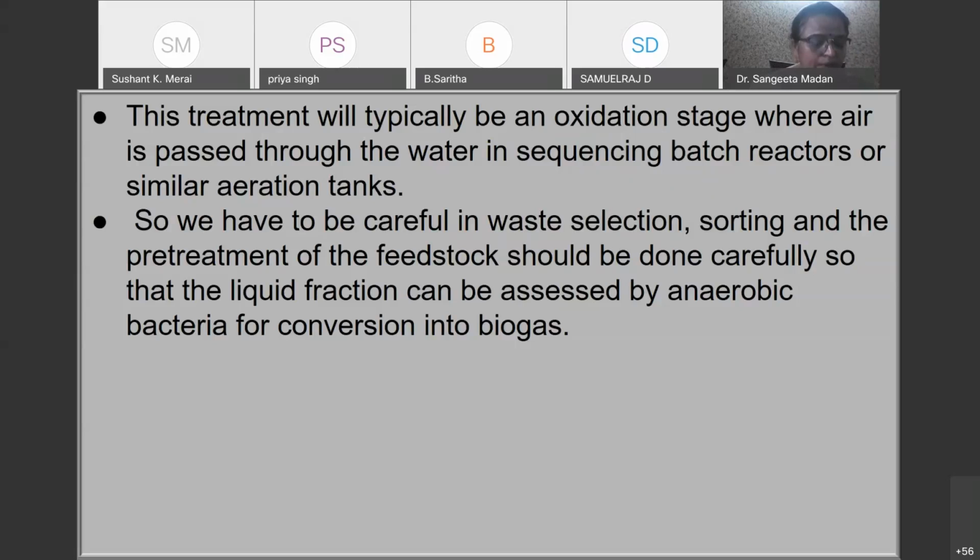So it needs to be continuously used, because we face difficulty in storing it. Biogas lamps have lower efficiency as compared to using kerosene. Gas production below 15 degrees centigrade is no longer economically feasible. If your gas production is low, below 15, it is not economically feasible.